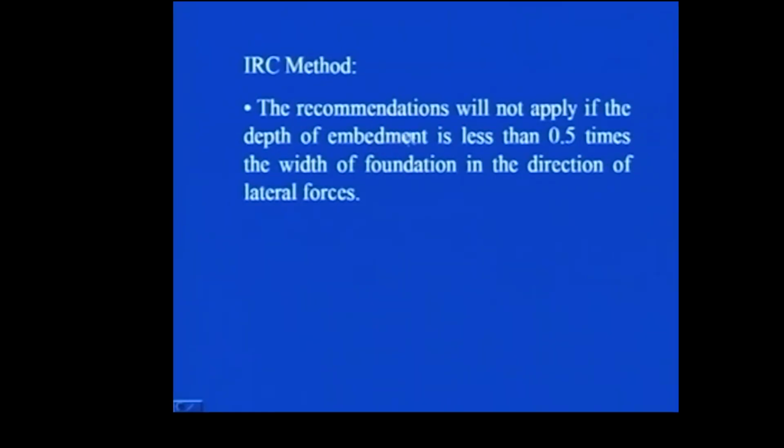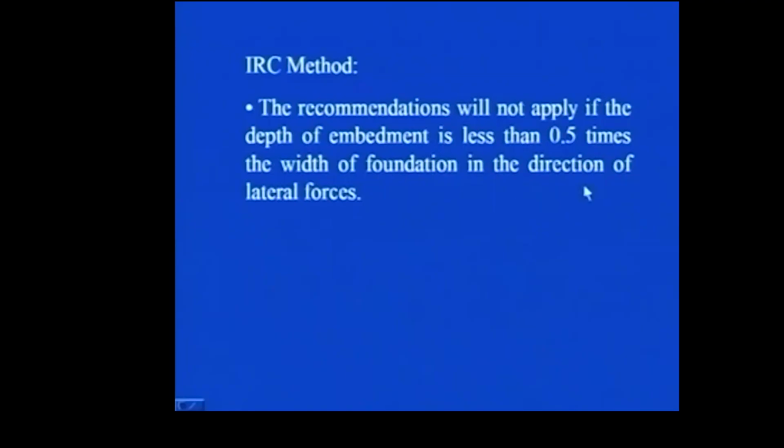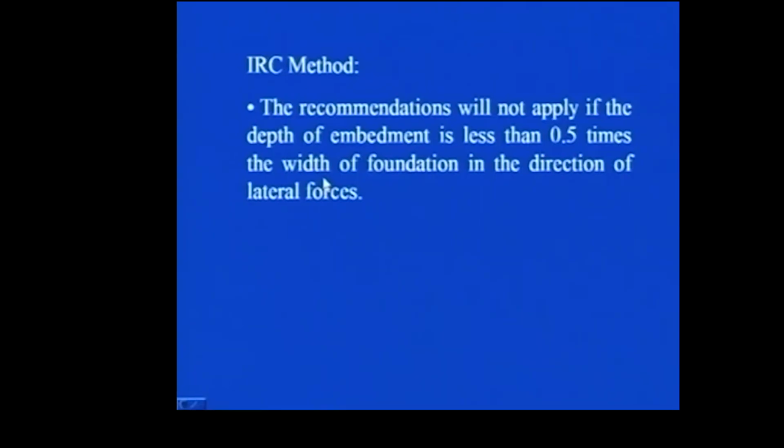Then the recommendations will not apply if the depth of embedment is less than 0.5 times the width of foundation in the direction of lateral forces. So, this is the limitation of this IRC method: if the depth of embedment is less than 0.5 times the width of the foundation in the direction of lateral forces, then these recommendations by IRC will not hold.